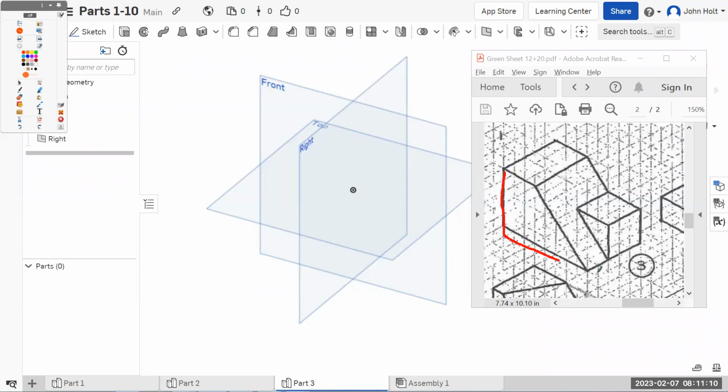We're going to start with just this wedge, which we've done similar things before. And we're going to extrude it 5. Then we just have to make this sort of wedge extension. We'll get to that in a second. So this first main part is 5 tall, 3 wide at the top, 8 across the bottom, and then connect, and then extrude 5. So it's 5, 3, 8, and then 5 thick.